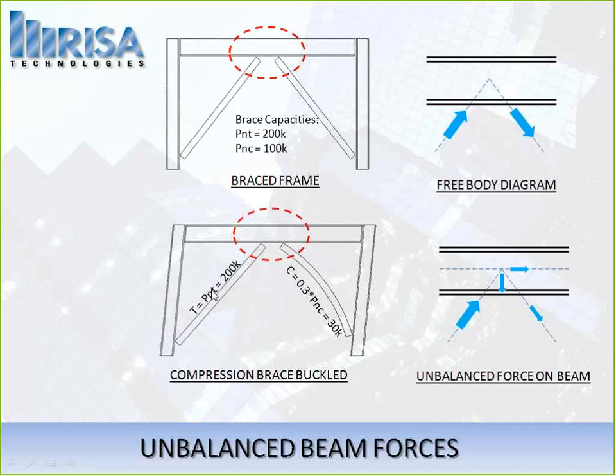So what we end up with is that some of the tensile force in this beam is resisted vertically with this brace, but that some of the tensile force from this brace is actually also resisted as shear in the ends of the beam, as this whole beam is now going to get pulled down or pushed up accordingly during the earthquake. So we need to design the beam for this unbalanced force.